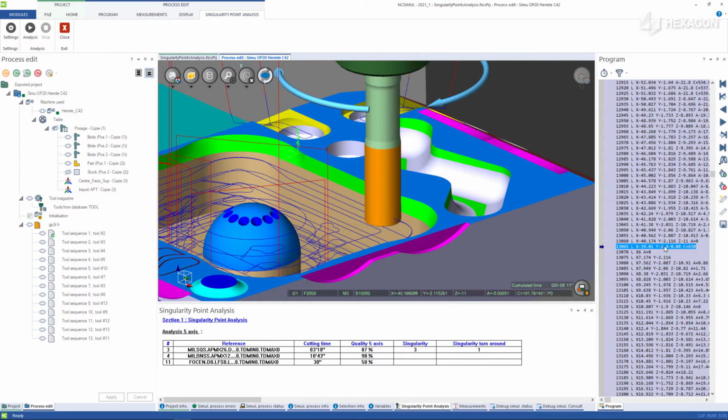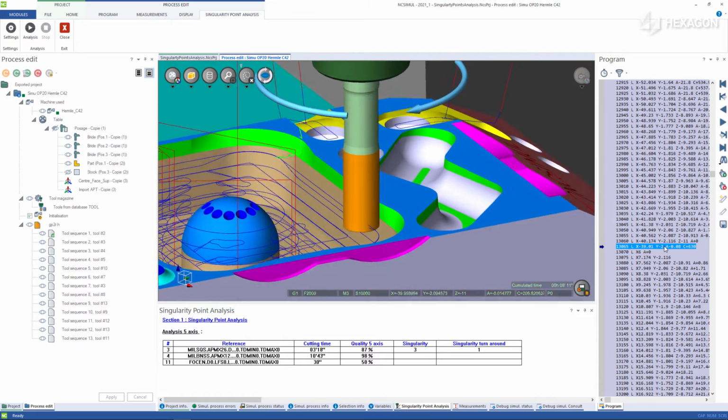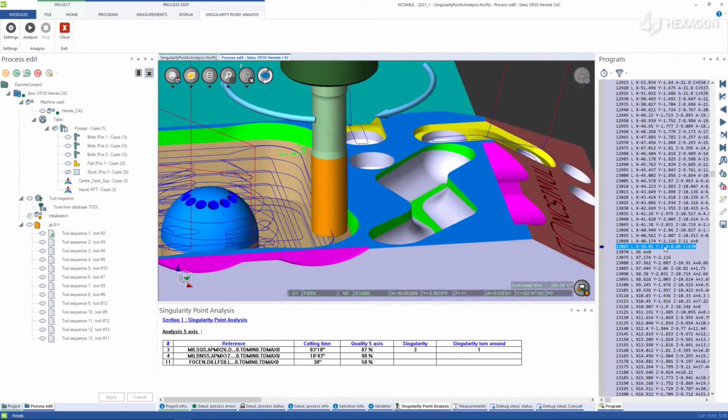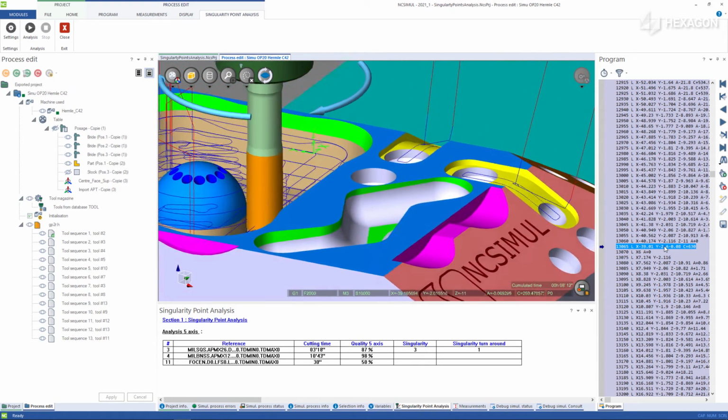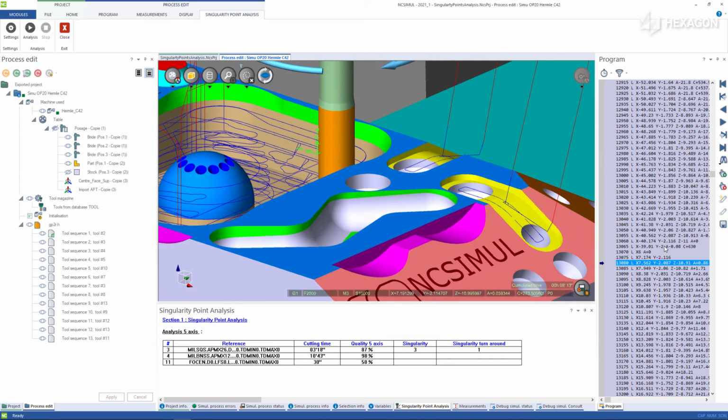In the turnaround field, for instance, there is nearly a 90-degree rotation on a single block while machining in 5-axis, which makes it nearly impossible to achieve a good cutting condition in that area. There is a long travel on the machine for a very short tool tip travel.